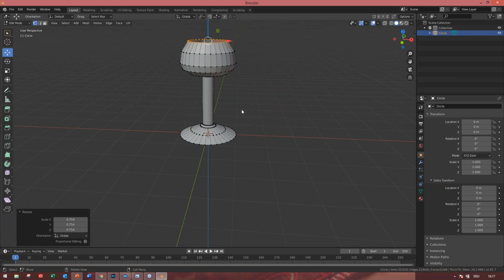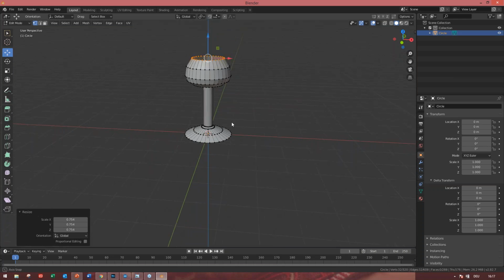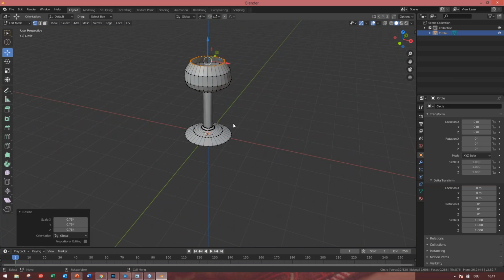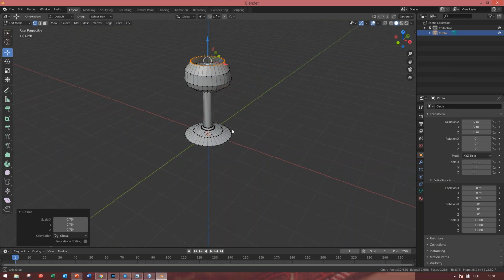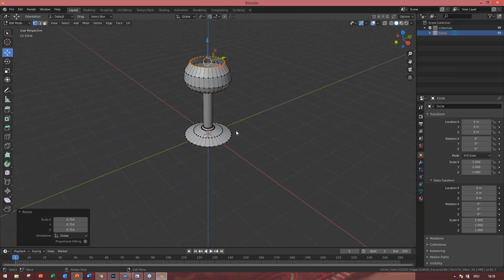But you have to be careful with this. If they are not necessary vertices you're using for more details, you will get a 3D object with a lot of vertices, and that will not be cool in Pandoras Box, because you wouldn't save performance with this.